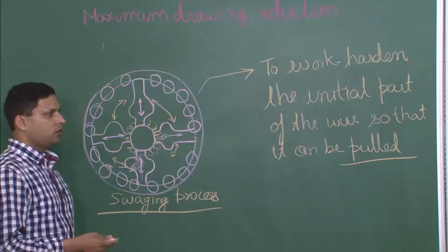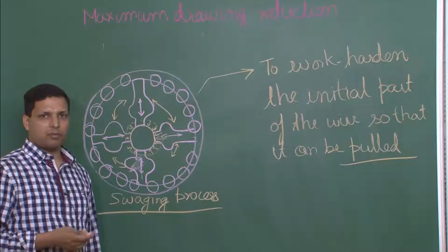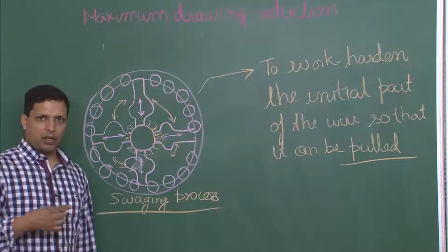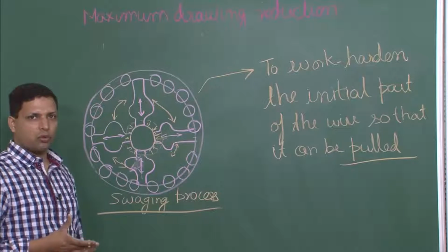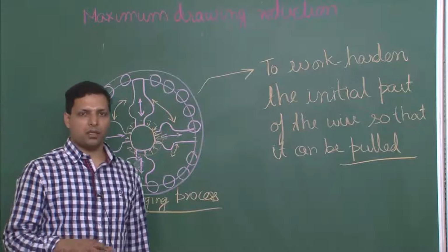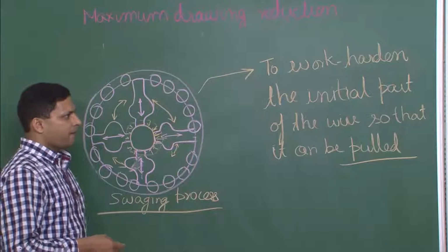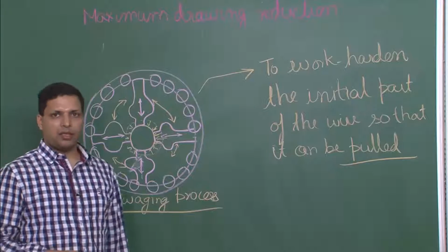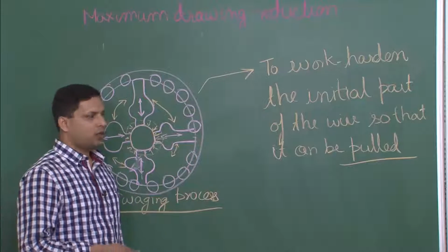You just need to calculate the integral of sigma bar d epsilon, which is ideally the real work that is going on. That is the ideal work, and then you can relate it to some of the external parameters assuming no friction. Now, we will go to another method as we promised earlier, which is our upper bound.